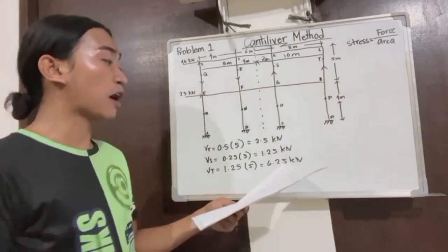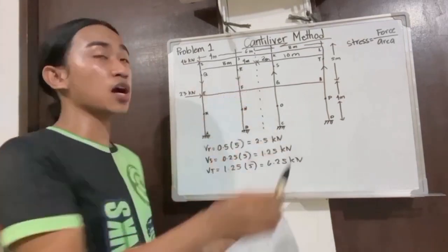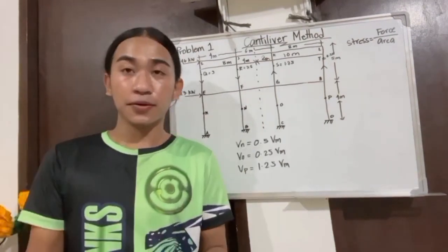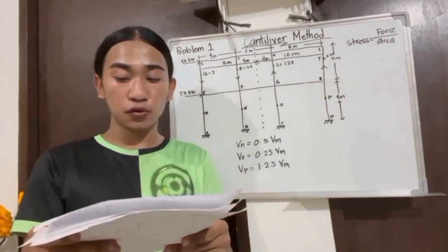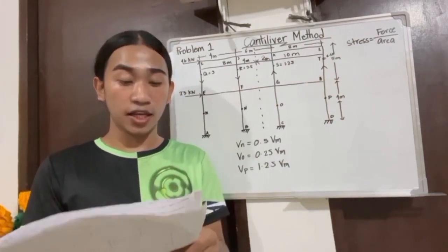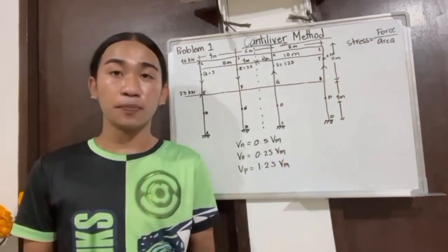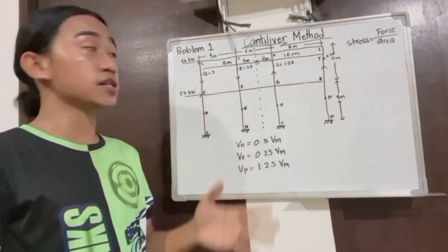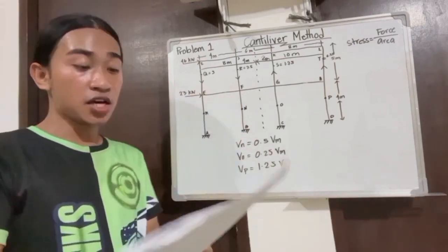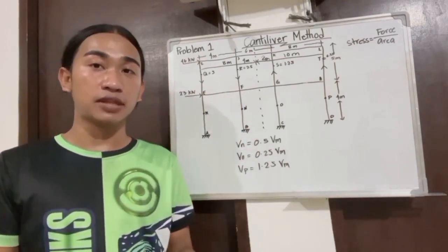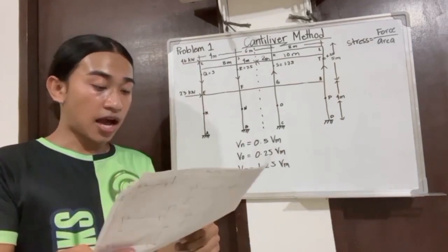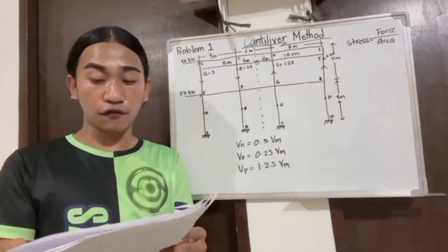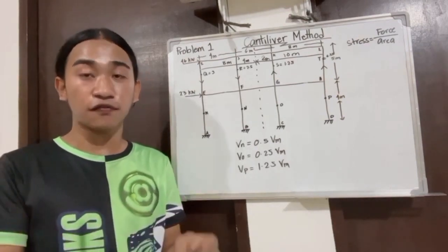So these are our values for Q, R, S, and T. These are the axial forces. So now, let us split the frame into two parts from the center of the column in the bottom story. Earlier we were at the top, so we got the axial forces Q, R, S, and T. Now we go to the bottom story. We have made the expression for the axial forces in terms of VQ.